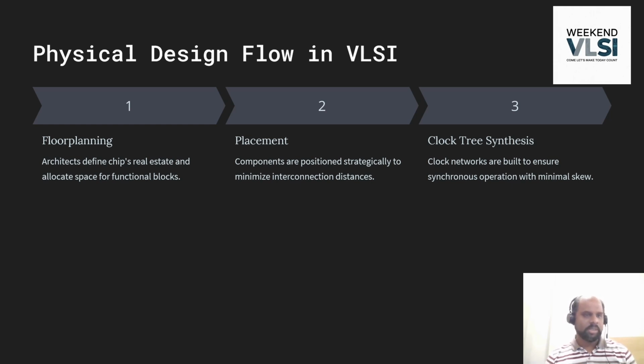What it means is that we are doing LDRC and DRC to meet the transition targets. Very simple. Okay. If the transition targets are not met, then the clocks will be very slow, and it will have a lot of issues like duty cycle problems, jitter issues, all those.